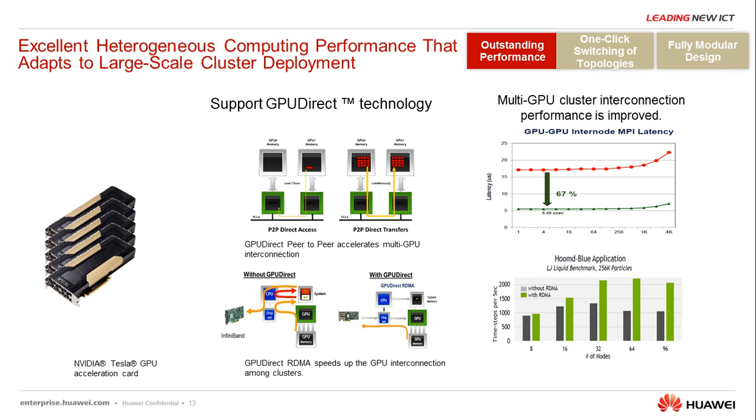By limiting unnecessary CPU processing time, the NVIDIA GPU Direct technology enables the GPU to communicate with other devices on the PCIe bus faster. GPU Direct version 1.0 allows third-party device drivers, such as drivers for InfiniBand adapters, to communicate directly with the CUDA driver, eliminating the processing time that would be needed for replicating data on the CPU. GPU Direct version 2.0 allows multiple GPUs in the same system to implement peer-to-peer communication, avoiding extra CPU processing time.